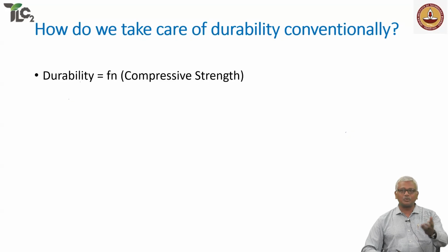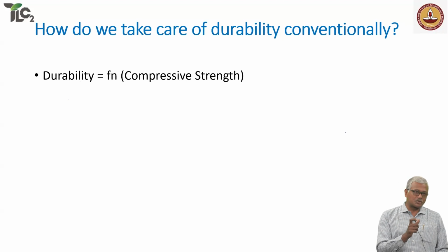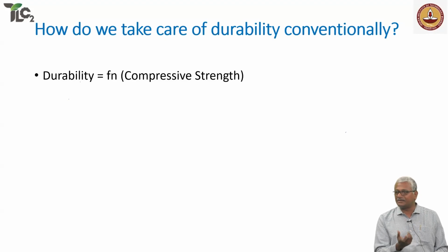One example I'll give you: in the Chennai Metro Rail project, they were designing these tunnel segments, which were supposed to be structurally only of 45 megapascal grade. Okay, but the durability condition was so rigid, and the specs did not allow for the use of supplementary cementing materials, because of which the concrete actually was designed for a much higher strength. When we actually took cores from these segments and tested, the strength of the concrete came to 90 megapascals, just to meet the durability criteria, right?